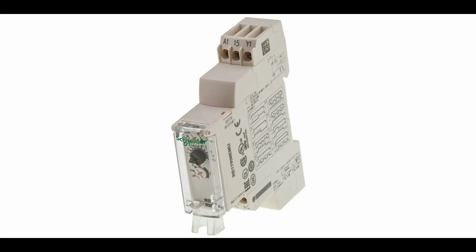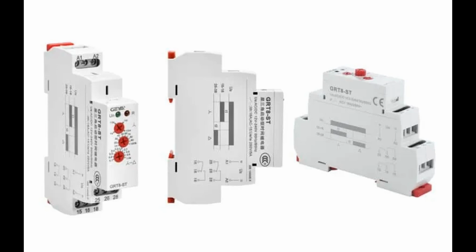HVAC, heating, ventilation, and air conditioning systems. Sequencing operations in heating, cooling, and ventilation systems to optimize energy efficiency and comfort. Delaying the activation of auxiliary equipment, such as fans or pumps, to prevent short cycling and improve system performance. Implementing time-based defrost cycles in refrigeration systems to remove ice buildup on coils.